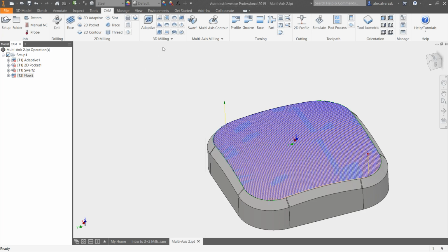Awesome. That helps a lot. And this is a really cool question, and I think we can emphasize this a little bit. Does the code attach to the .ipt file? So the Inventor part file itself. Alex is doing all of this in the Inventor part file. Save the part file. All of the toolpath setup and stuff is in that part file.